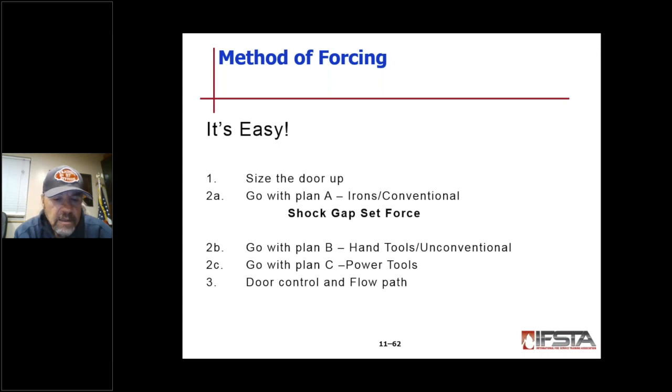Keeping the door open allows a flow path for air to get into the building, and it can create serious issues for fire control in other parts of the building. Even on the very far side of the building, a window or a door open on the opposite side will cause fire conditions to change significantly.